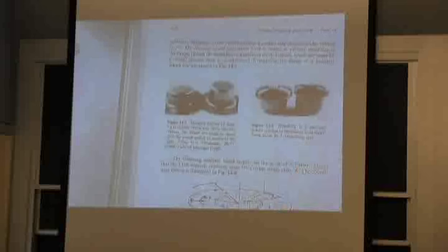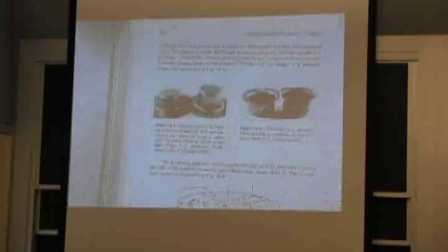This one has a very sharp cube texture, and you can see I have different deformation in the 100 direction than the 110 direction, okay? So I get ears on my cup. And of course that's going to have to be cut off. I have to use more material, and I have scrap if I get earring. So earring is something that people will often try to specify: that you have anisotropy to give you a good R, but you don't want anisotropy that gives you planar anisotropy, which gives you ears, which wastes material.